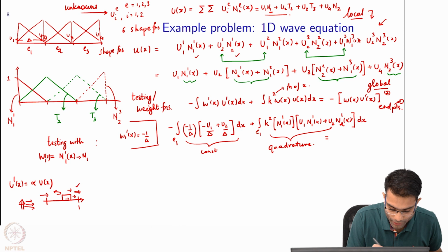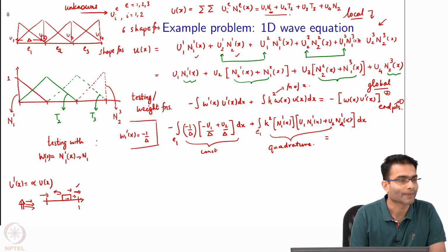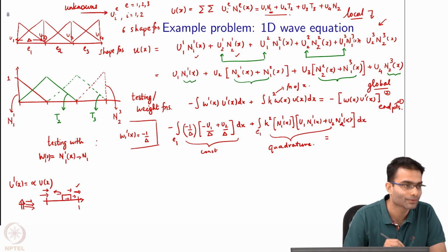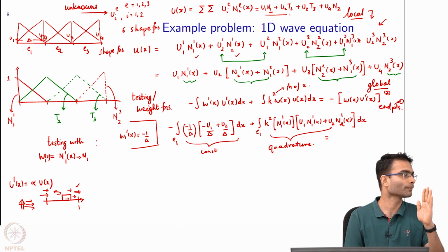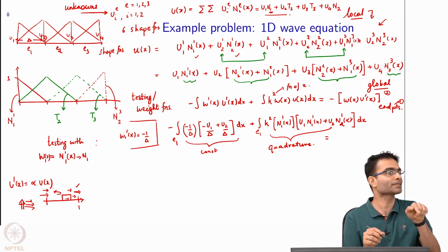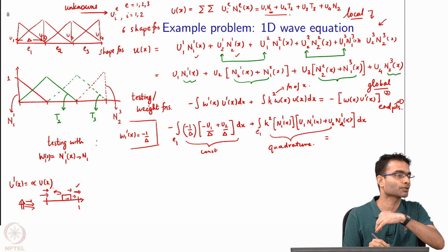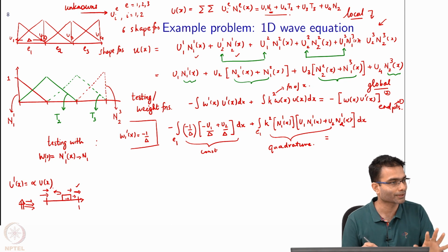So, here there seems to be no problem, but when I come here, what is happening? Incident field is actually going in the opposite direction from outgoing. The scattered field is the part I should not allow to come back into the simulation domain, right. Incident field I do not care about, it is given by a mathematical expression.